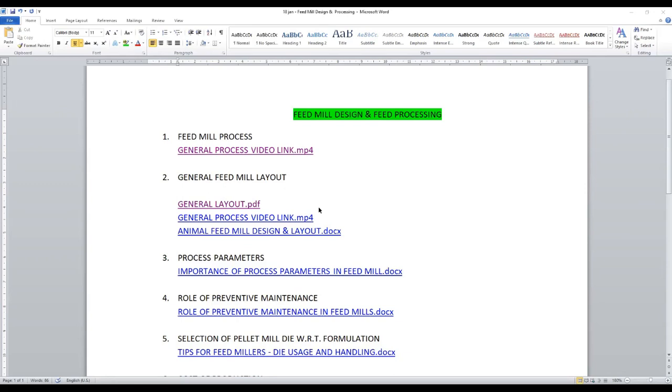If we check the theoretical calculation of the warehouse on the internet or in other books, there is a specific space required for ventilation, passages and all other things, and there is a stacking limit, that up to 15 or 18 feet we can go. We have a thumb rule. We discussed with 8 to 10 feed millers and noted down their warehouse size, and asked them, when they fill the warehouse 100% up to the stacking height in season, how much grain storage they get.